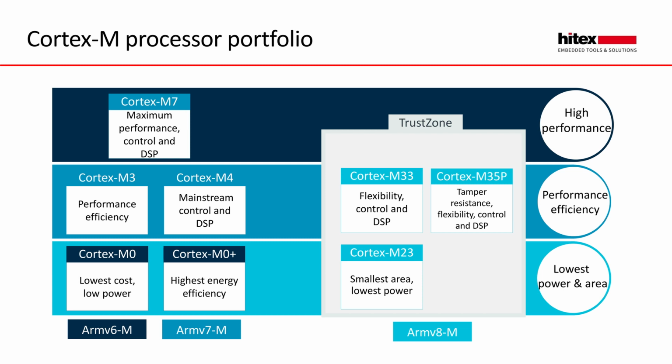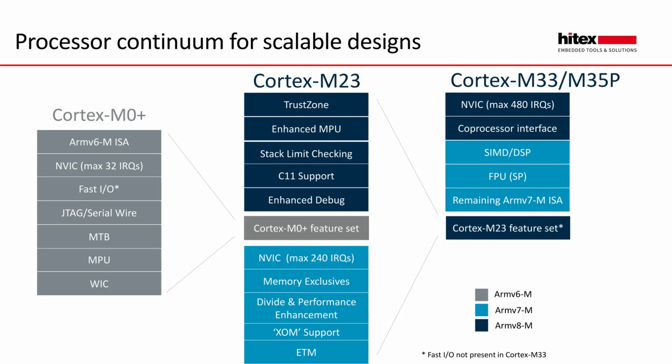When we need to access secure functions and data, we can make calls to functions in the secure world. These will execute and then return back to the non-secure code. Essentially, we have a small bit of startup code in the secure world, and then we pass over, and our main execution is within the non-secure area. We really want to try to keep the amount of code in the secure world as small as possible, so we can easily monitor it, and it just provides the security functionality.